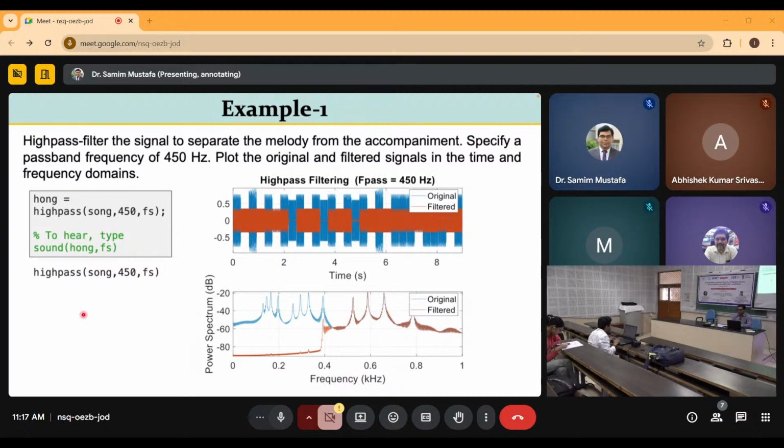So suppose the fundamental frequency of the bridge is 3 Hz or 4 Hz, whatever it is, based on the length and geometry and other specifications of the bridge. So we want to eliminate the frequency above that one from the response to preserve only the static one. Okay.